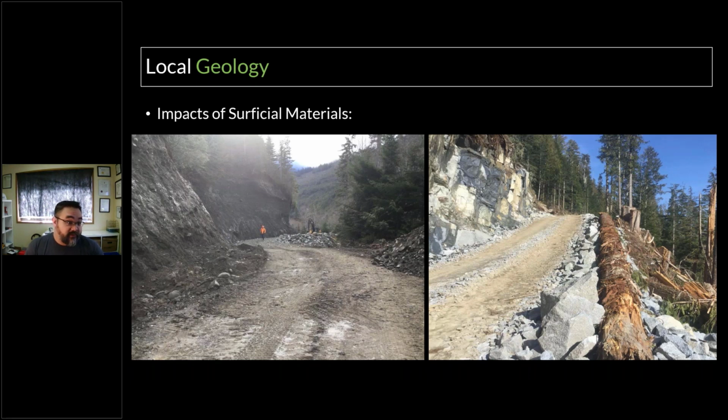You can put it in areas where there's more water, whereas the till on the left is a silt till. That's not going to stack at the same angle, it's not going to have the same internal stability, and it's certainly far more sensitive to water. So how you deal with those two different materials is totally different. Understanding that ahead of time, before you dig into the slope, might change where your spoil sites are, how many spoil sites you need, and how much management those spoil sites need.